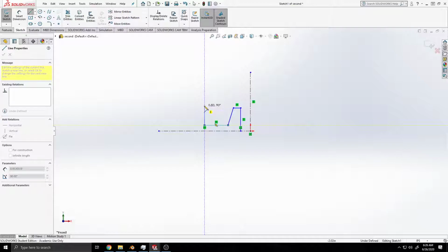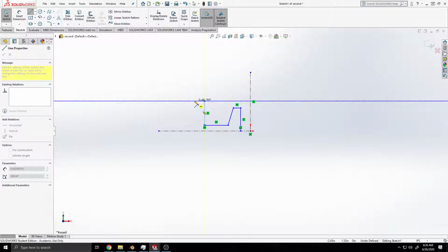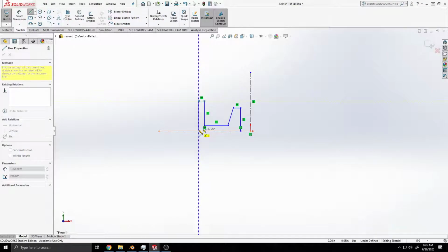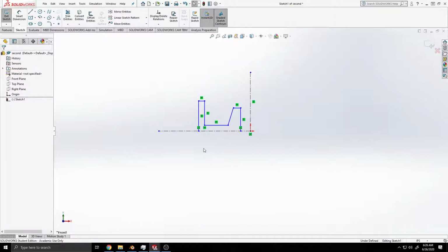Click. Drag across a very short little line that's eventually just going to be 0.25, so less than a 1/2 inch definitely. Click. And finally, draw vertically down and connect to the horizontal center line. Click again. Hit escape on your keyboard to get out of the line tool.